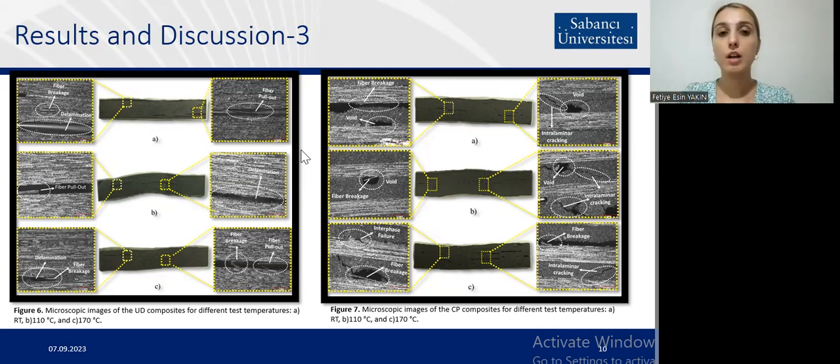The crack formation was observed at the free edge at room temperature for the UD, while when the temperature is increased, the crack formation occurred in the middle region, and this is the result of local stress variation. This local stress variation leads to residual stress variation in the unidirectional, and this residual stress variation reduces the stiffness and the brittleness of the unidirectional specimens.